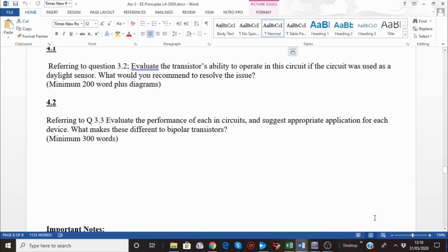So how would this operate? The transistor would get hot and eventually burn out. It's not a good design for that kind of application. The reason is because there's always going to be some leakage. Like I mentioned earlier, there is always going to be a voltage and a current going through base emitter, and the base collector is also switched on, is short but still has current going through it, and it just heats it up, and eventually it burns the transistor.